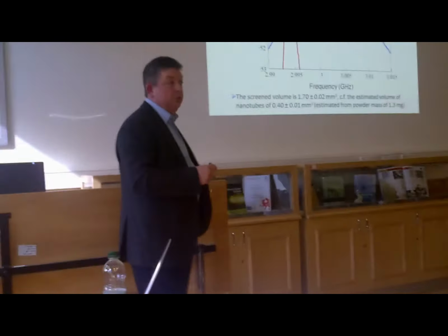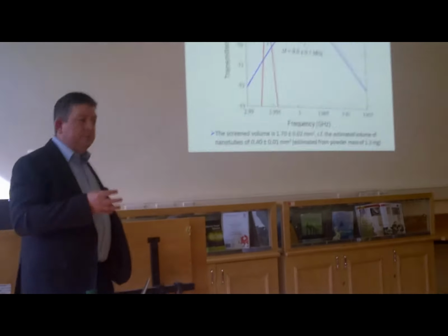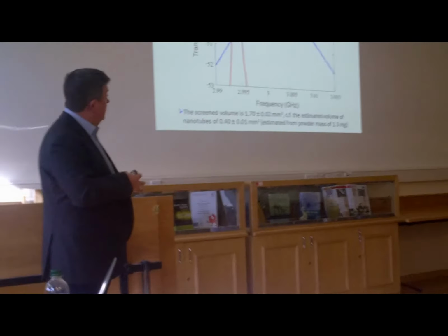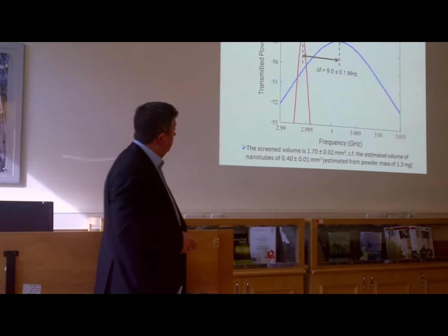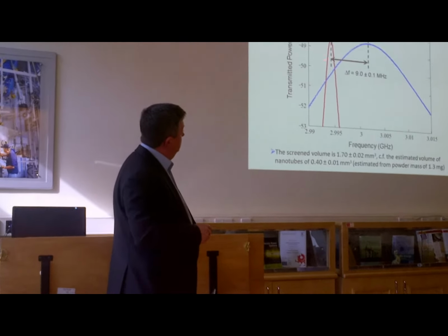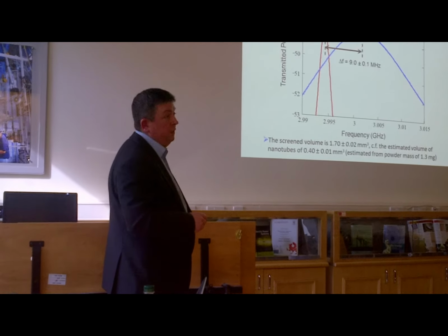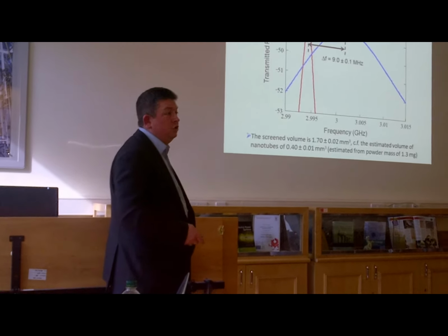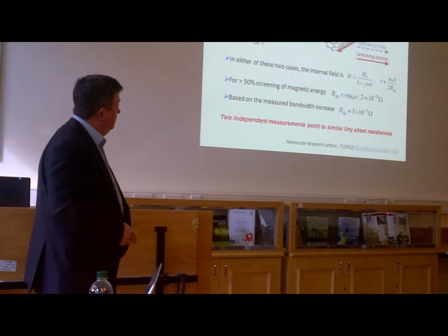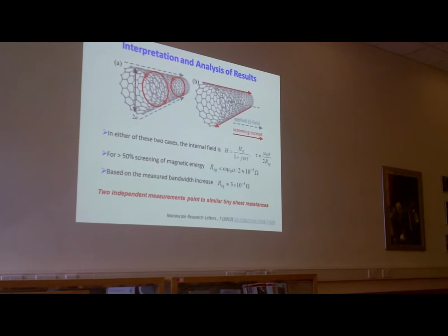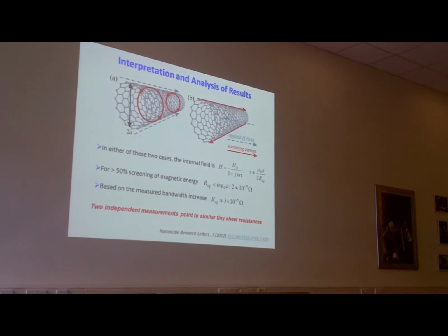And there's a very simple answer to that. If you could pulverize these nanotubes flat, so that they covered just a plain area, then I think it works out that 1 milligram covers 22 square metres. That's how much area there is to them. So you get a massive broadening of the bandwidth, not because the sheet resistance is high, but because the sheet resistance is so low that the area is massive. And that's what's giving you the broadening.